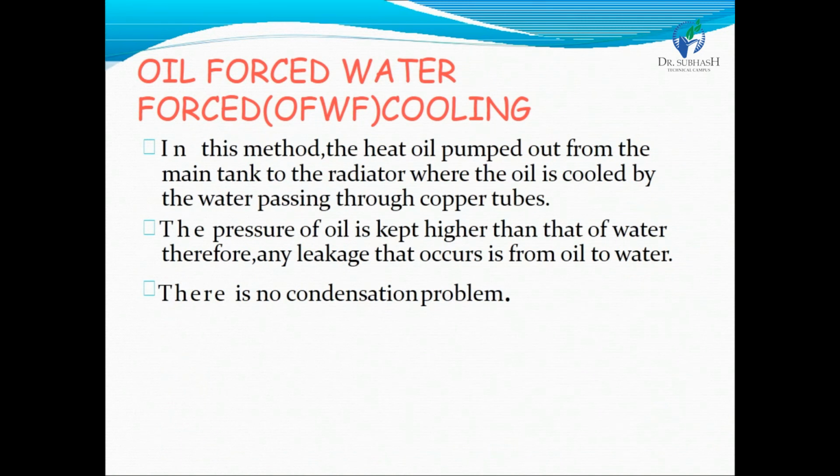Now, the next topic is oil forced water forced cooling system. In the oil forced water forced cooling system, used in large transformers, this type of cooling needs a heat exchanger. Inside the heat exchanger, the heat from oil is transferred to the cooling water.